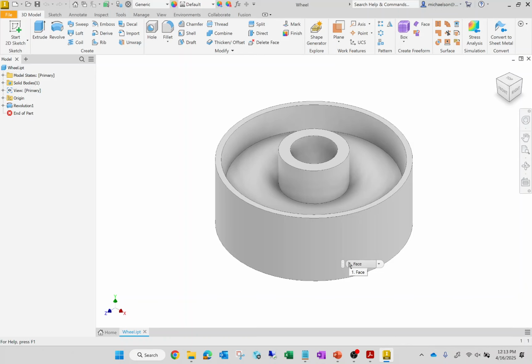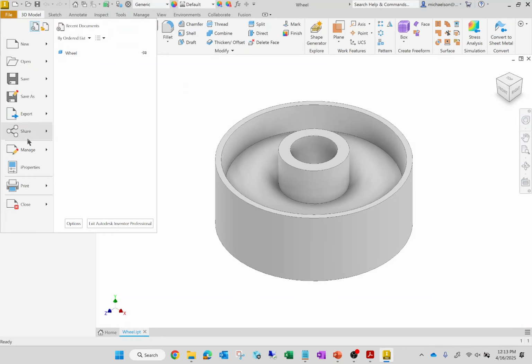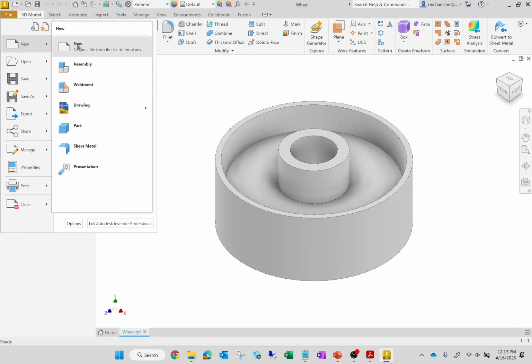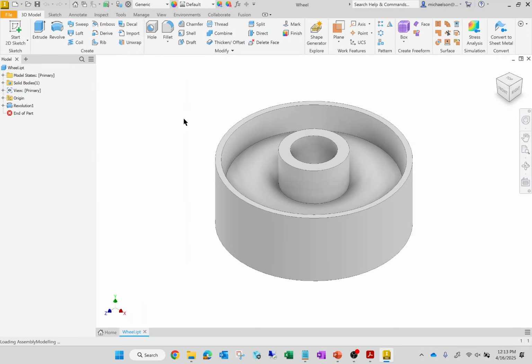Okay, now again, this should be fairly simple if you understood how to do the drawings last time. There is going to be one difference from what we did last time. We're going to do a section view, and we didn't do that on Monday. But by and large, the drawing creation should be pretty straightforward. So I'm going to go through some of the basic stuff pretty quickly. I'm going to hit File, New Drawing, and then for here I'm just going to use the template.